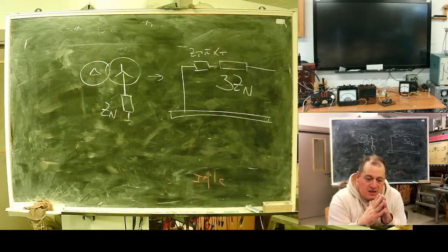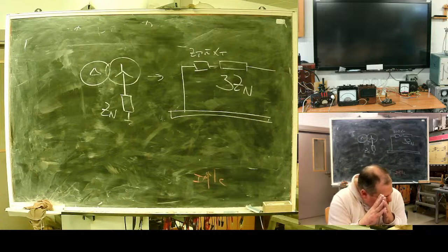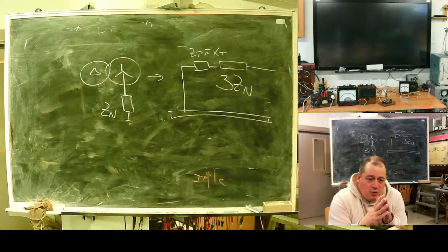For overhead lines with sufficient distance between wires, for example 110 kilovolts, about 0.1 active ohm per 1 kilometer, and 0.4 reactive ohm per 1 kilometer. It's a typical figure for direct and negative sequence. For zero sequence, effective resistance is approximately triple, so 3 times higher.